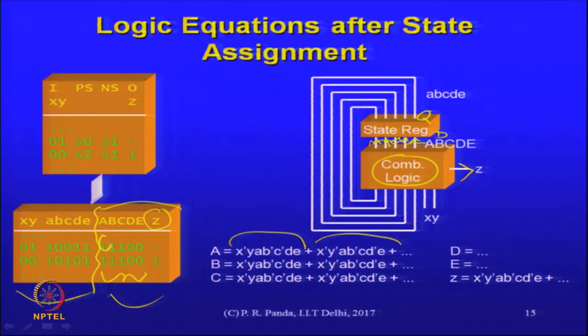One of these terms should correspond to that row, being 1 for A, which means that we will pick up the corresponding input here. First, let us look at the xy. So, xy is 0 1, so that is my x prime y. A, B, C, D, E, we had S0 there, this is the encoding for S0. So, I have B prime C prime and A, D, E, that is the expression. So, that is what I have here. So, that is my expression corresponding to these inputs. Okay. Then the other one would correspond to picking up that expression, that is what I have there.